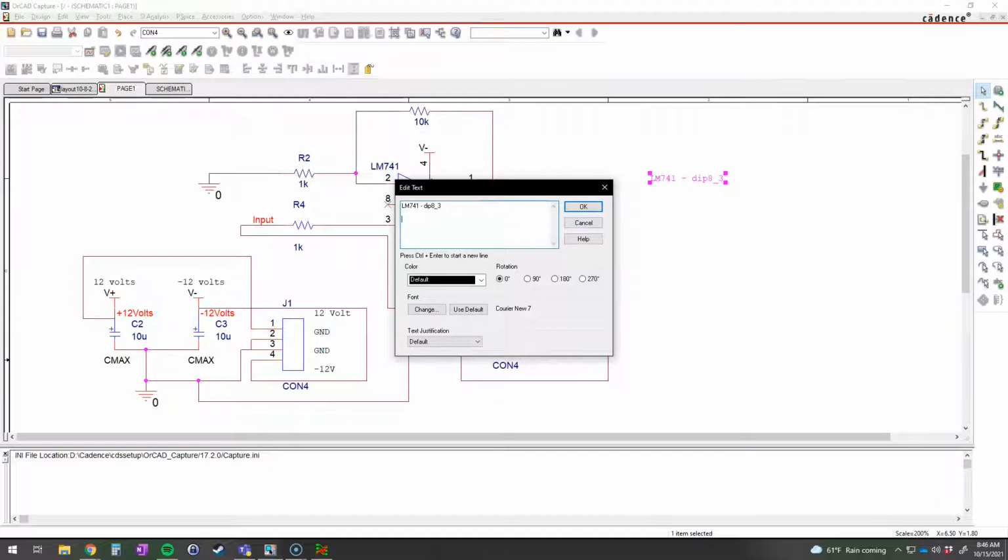Now for the headers, J1, J2, those footprints would actually just be jumper4. Then for my resistors, the footprint would be, and this is a little bit longer, AX, which stands for axial, 375, that's in mils. 375 mils long is what we're saying the resistor is.